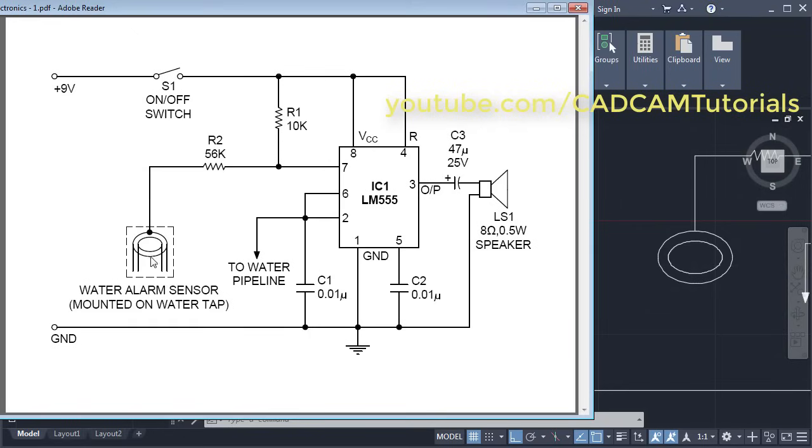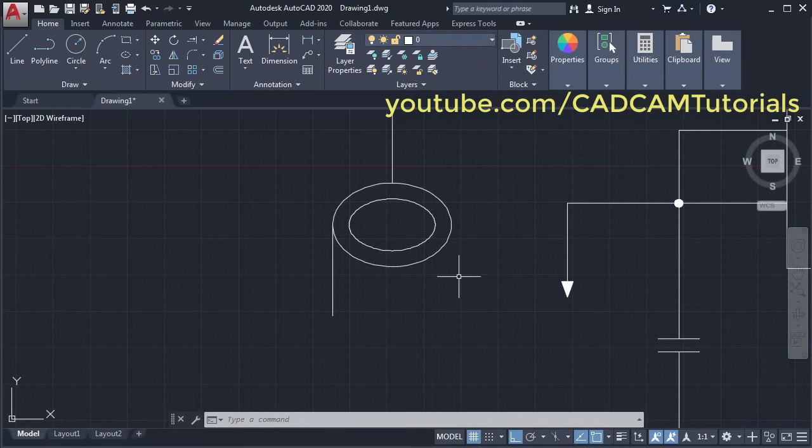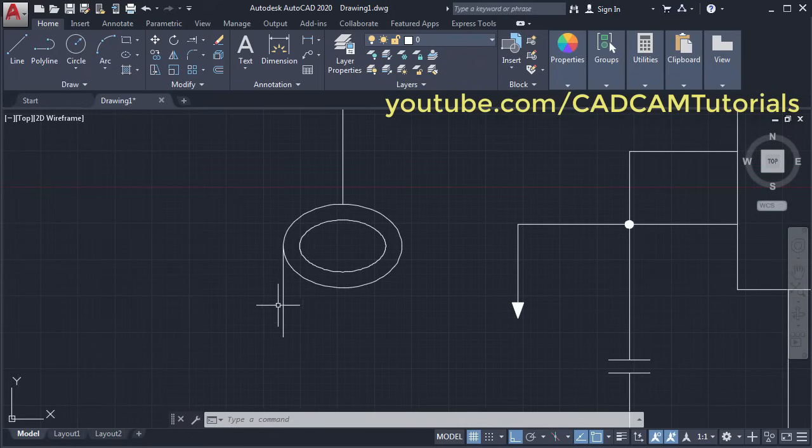Then these vertical lines and this rectangle. Click on line, click on this quadrant point, take your cursor below and click and press enter. Then we will offset this line, click on offset, then press enter, then select this line and click on this midpoint. Then again select this line, then this endpoint, select this line, this endpoint, quadrant point, enter.